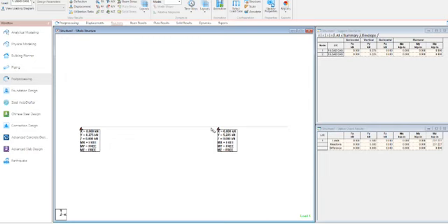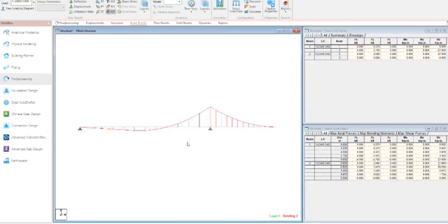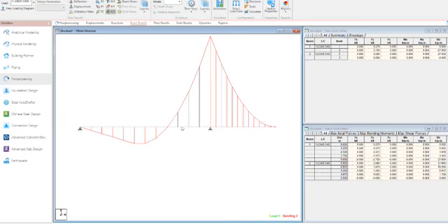That's in kilonewton. So reaction if you see 5.225 at this corner, at this joint. So remaining is 0.25. So this reaction is upwards only. This is positive. That's why if you see bending moment, we can see there is a sagging bending moment and hogging bending moment.